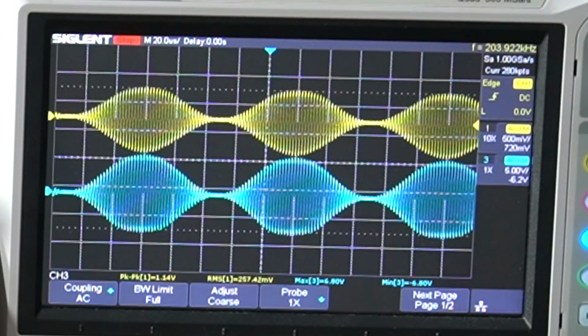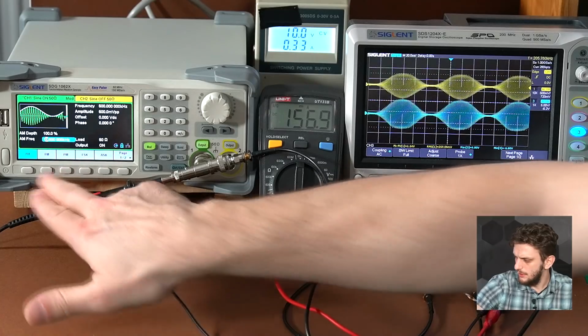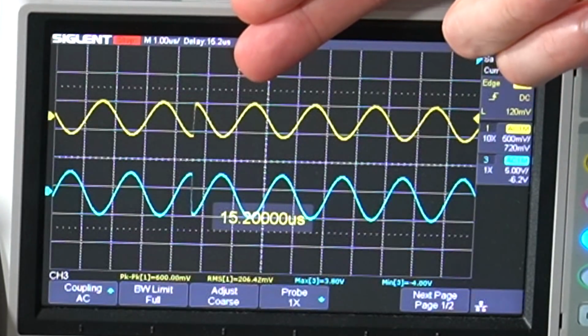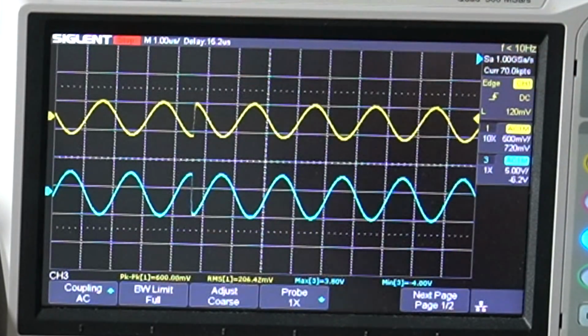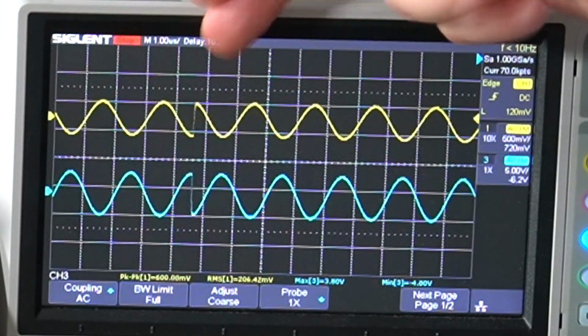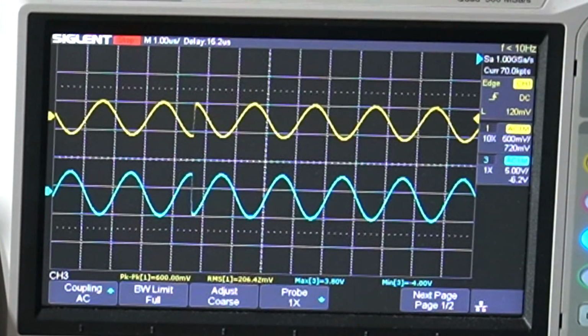Otherwise the two signals are quite identical. Next we can try out phase modulation. This is a type of modulation in which the phase of the signal suddenly changes. We can see it on the input signal: we've gone from one phase to a completely different phase, the frequency stayed the same, but we had a very sudden change, and we can see the same thing on the output.